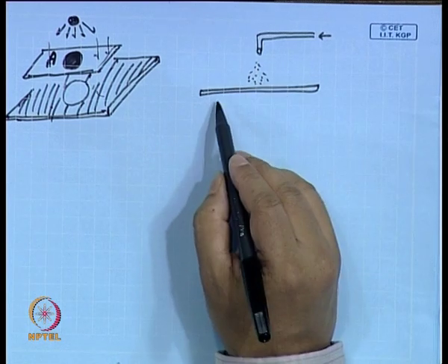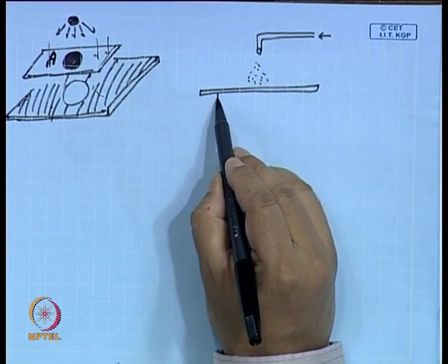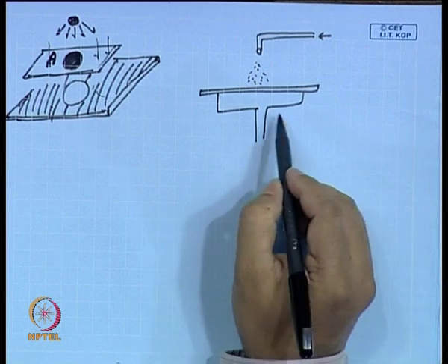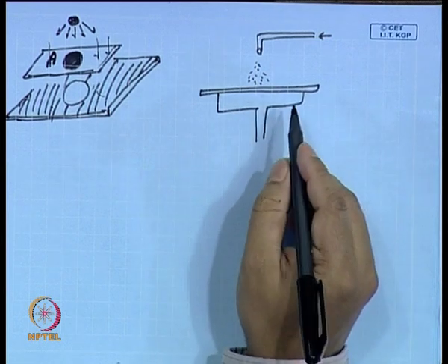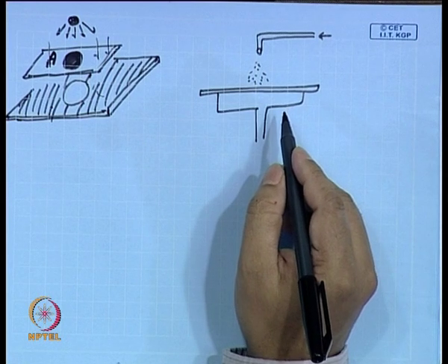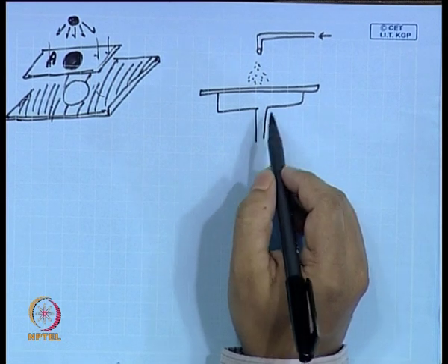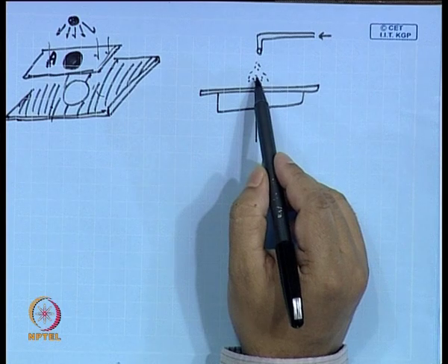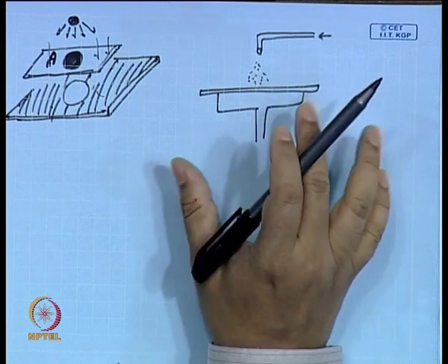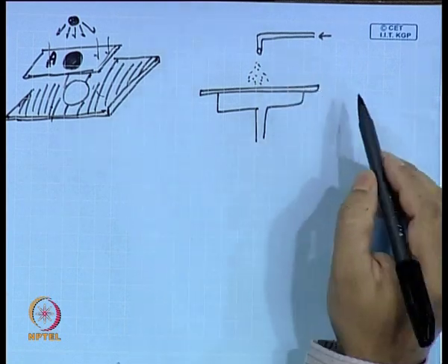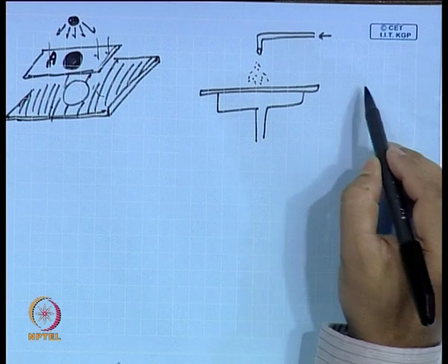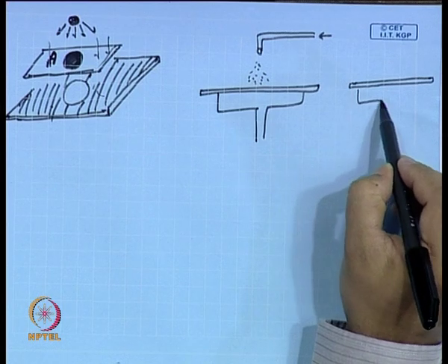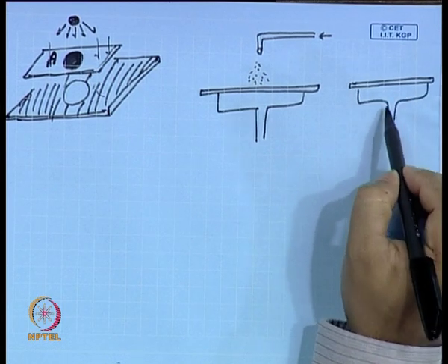And then what you do is rotate this wafer at a really high RPM, initially maybe 1000 and then going all the way to 8000. Moment you rotate, what will happen to this resin material? Because of centrifugal force, it will start spreading out, right? Suppose this is the wafer and this is the chuck, called the chuck, which holds the wafer.